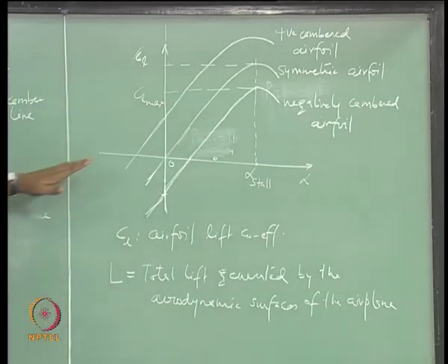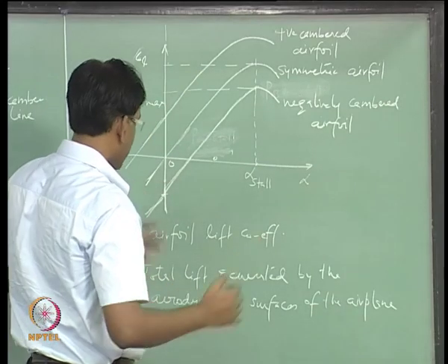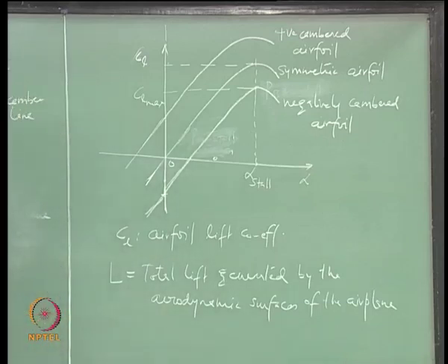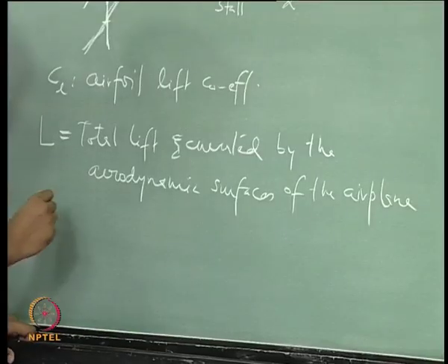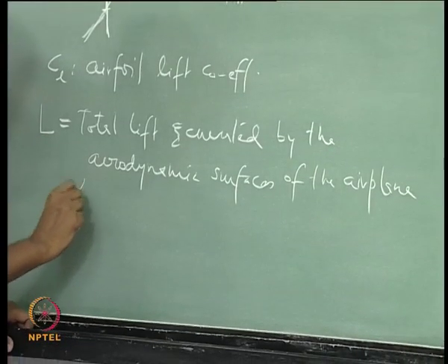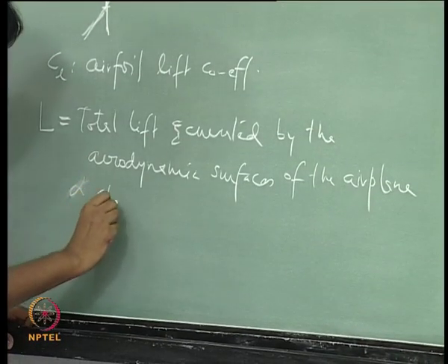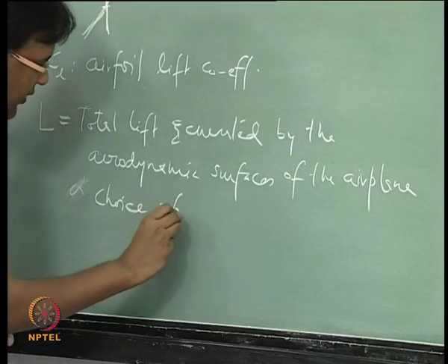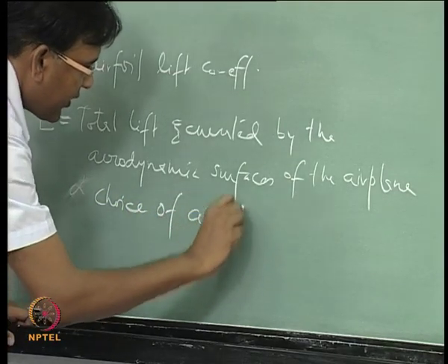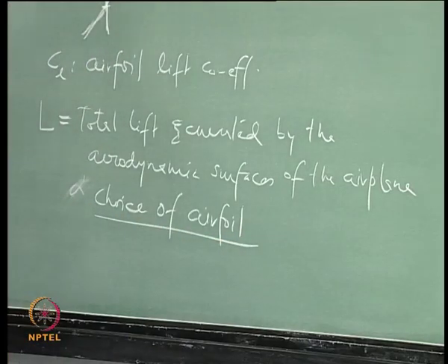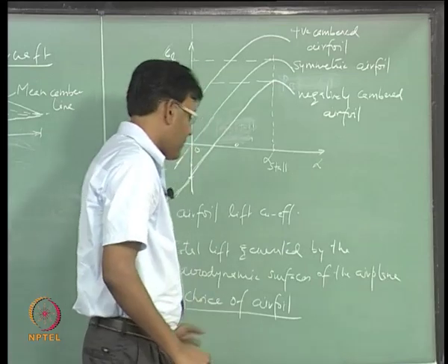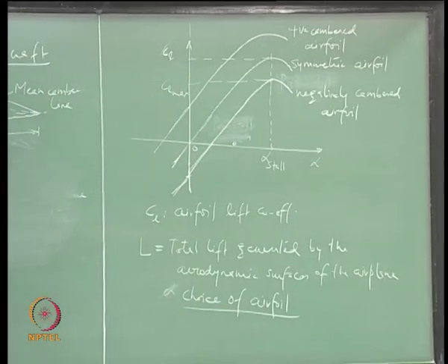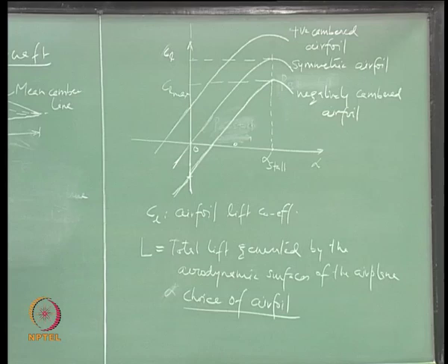So, in case you have chosen this positively cambered airfoil for the wing, that is going to give you much higher lift as compared to the other two airfoils. So, this is clearly depending upon the choice of airfoil. Choice of airfoil is also depending upon the regimes of flight that you want to fly.